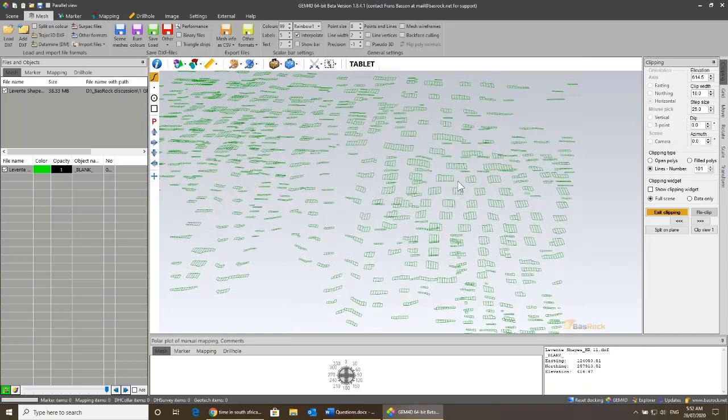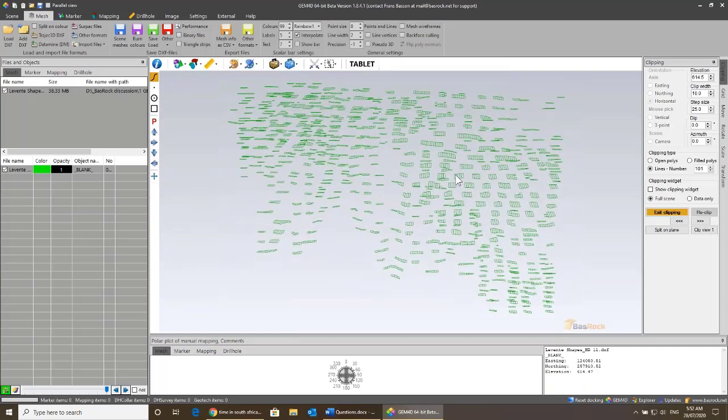Sorry about that. So now I'm off my story a bit. Well, yeah. So if you go for an odd number, you always get the elevation that you selected. If you go for an even number, you actually get half that offset above and below the point that you selected, and not exactly the point that you selected. So always go for an odd number. Okay, so I've created my sections.